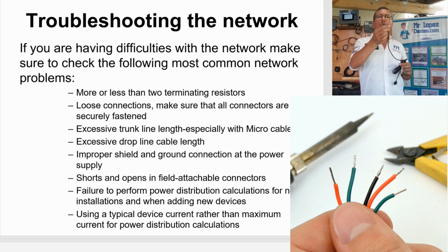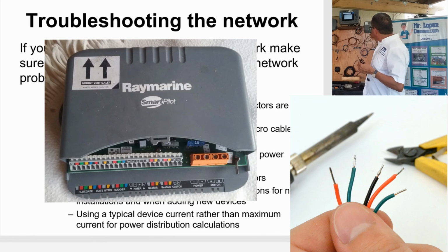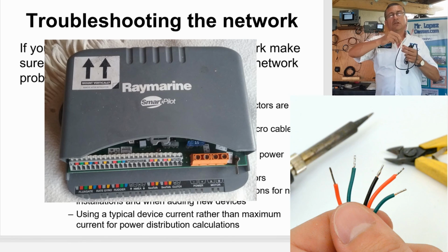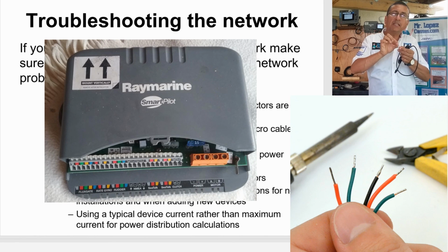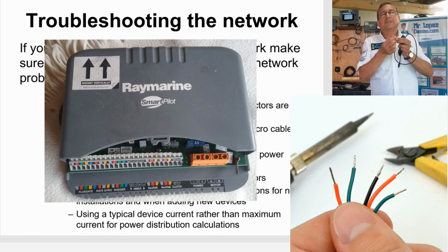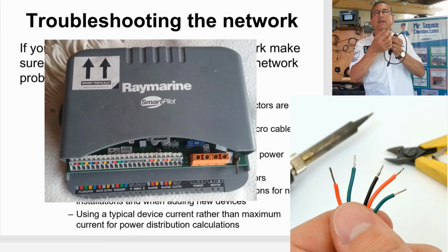For example, I want to connect this cable directly into the computer, directly into the terminals. The recommendation is to immediately remove the plastic, solder that terminal with the soldering gun, and after that it is easy to introduce those cables. After that you don't have loose wires around, and you don't have the possibility of interference.